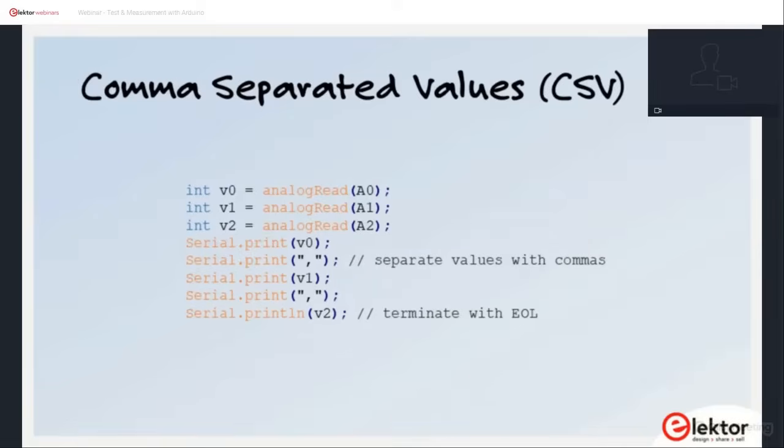If you have recorded samples, timestamped or not, then a better way to visualize them is by sending them to a computer to process them in a spreadsheet. A good way to do this is by sending the samples over the serial port using the human-readable CSV format, comma-separated values. It doesn't have to be a comma, often a tab or a semicolon is fine too. Most spreadsheets can import CSV files directly, saving you the hassle of writing Python scripts to convert binary values into something usable. In general, I highly recommend transmitting, whenever possible, human-readable data over a serial port, as it makes debugging so much easier.